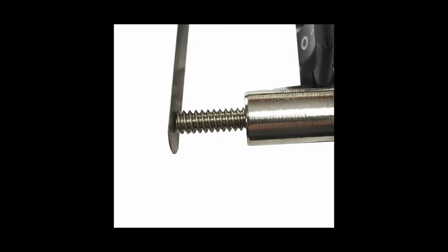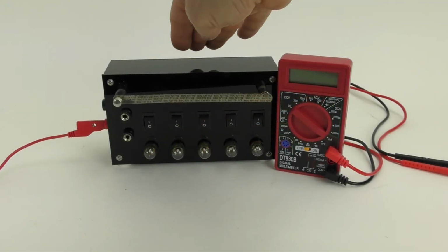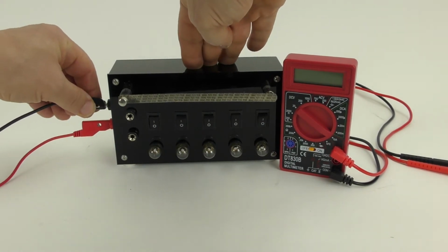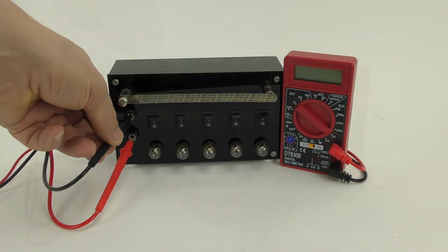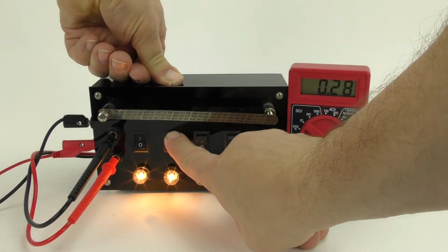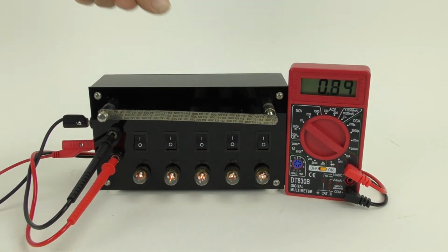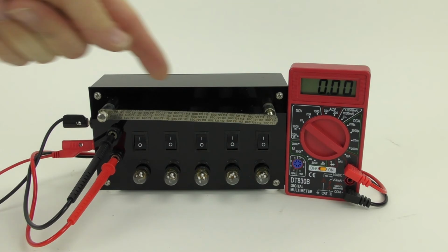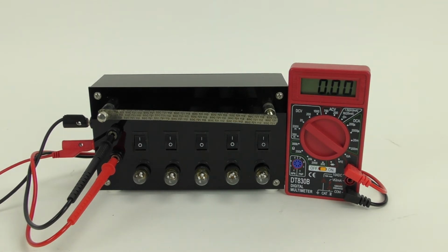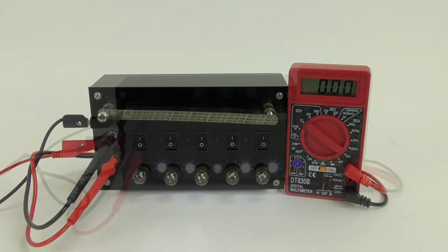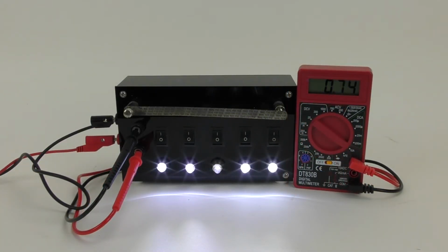So as the bar heats up, it will bend away, breaking the electrical contact. Next, you connect a power supply and then a multimeter set in ammeter mode. Eventually, the current will heat up the bimetallic bar, and as you can see, it already bent away enough that it is not making contact, therefore cutting the current. If you repeat the same experiment with LED bulbs, you'll notice that the current is significantly less.